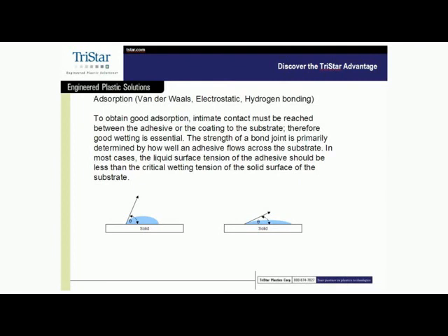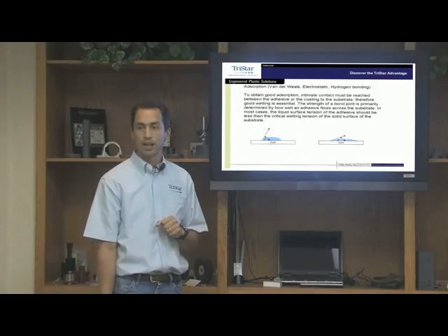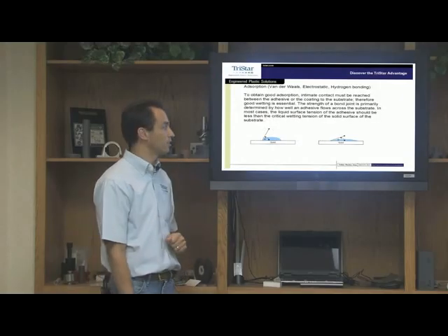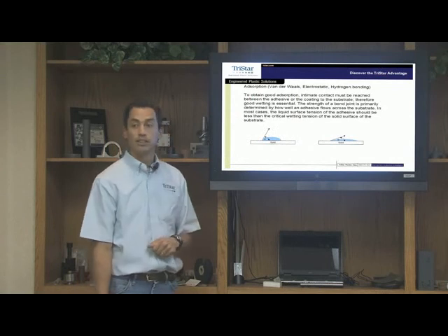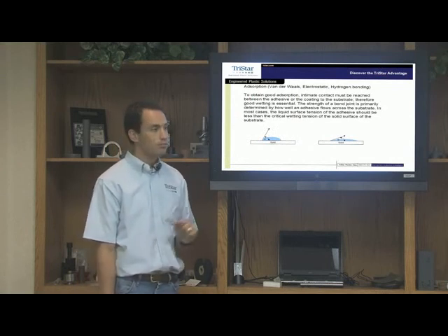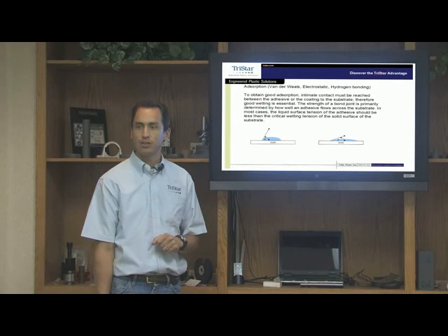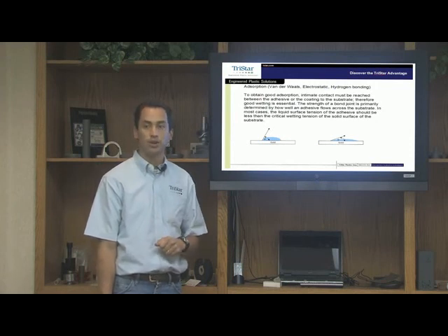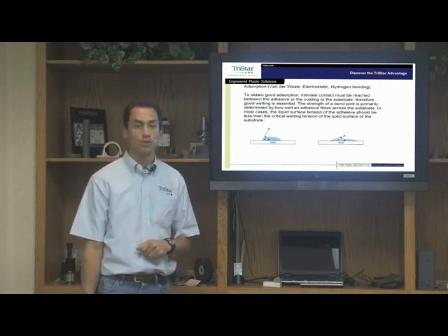After we do our plasma activation or organosilane deposition, we usually get a physical trait of wetting. When we dispense the same drop of water on that activated surface, the water will flow to its maximum reach based on the quantity. When we see that property, we tend to know, as a general rule of thumb, that the adhesive or coating will stick most aggressively.